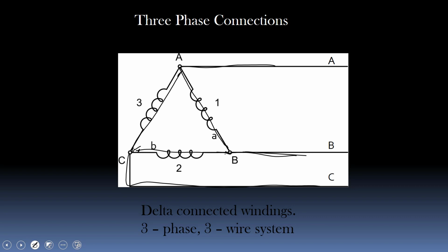So we're talking about these ends of the windings. You're going to see me using the terms little a, big A, little b, big B, big C, and little c. That's basically a way for us to help when we are connecting for the polarity of these windings. It's quite important, the polarity of these windings, with the direction of induced voltage, that we do that. If you've been setting up transformers, you'll notice there's an X1 and an X2, and that coincides with this. It's the same principle, the polarity of it.